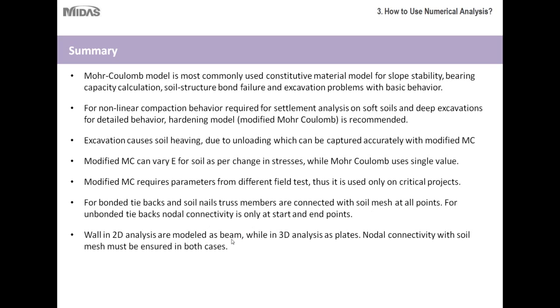Walls in 2D analysis are modeled as beams, while in 3D analysis are modeled as plates. So once again, if you go to 2D or 3D, the element types that you use go up a class. Nodal connectivity with soil mesh must be ensured in both cases.